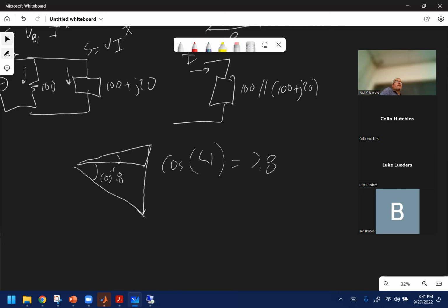Yes, sir. Since it's kind of a better power factor, are you saying it's a trick question, or is there one right answer you want to communicate? The right answer was X sub C, or C, equals 0. It already exceeds 0.8. Don't add a capacitor.